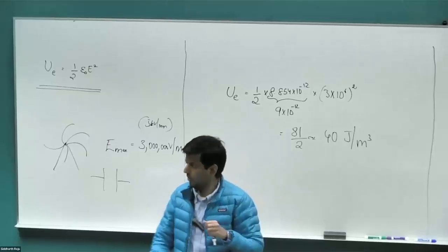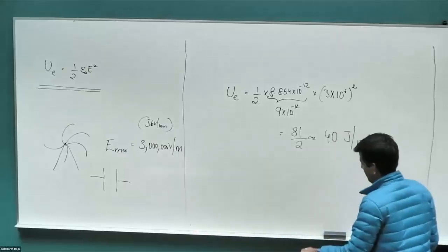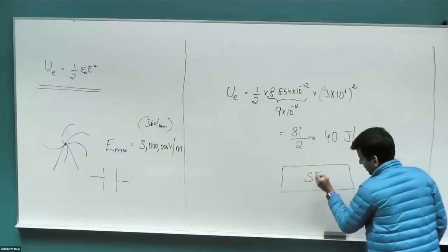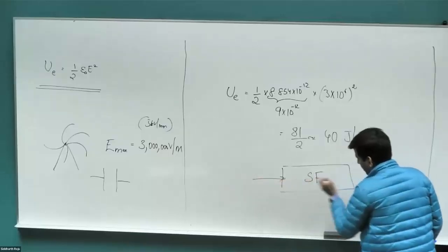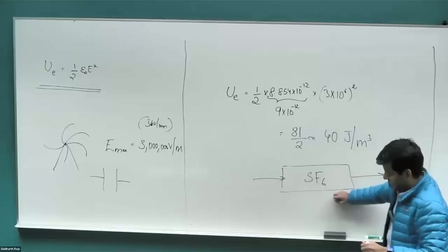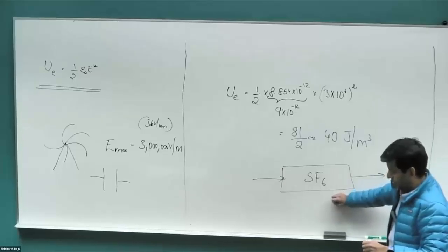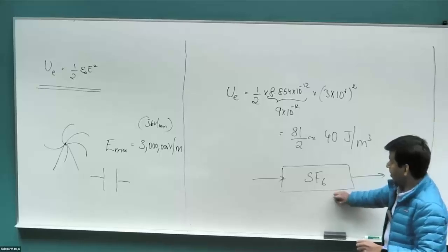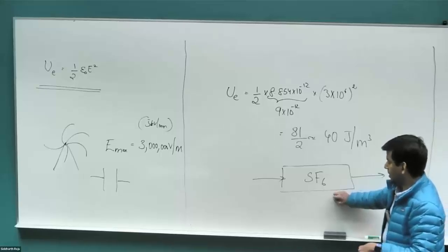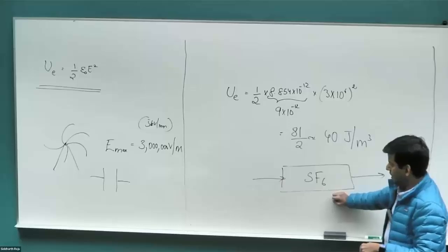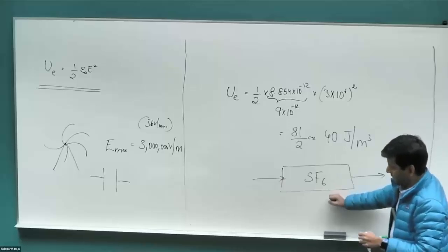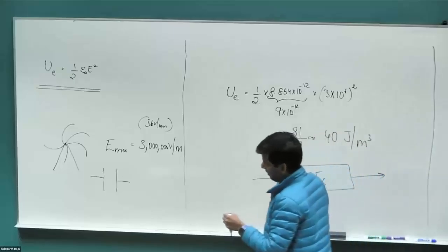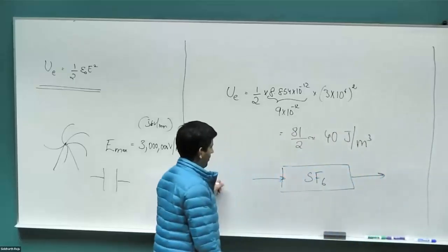So the one way they do it is have an enclosed switch gear that's filled with SF6, sulfur hexafluoride. It's an extremely potent greenhouse gas. I think it's almost 20,000 times more potent than carbon dioxide, and it lives for a very long time in the upper atmosphere, doesn't decay quite easily. So it's a very big problem. It's still used in switchgear because it's one of the best materials available, but it's a very potent greenhouse gas that people are trying to phase out, but no better material has come out.